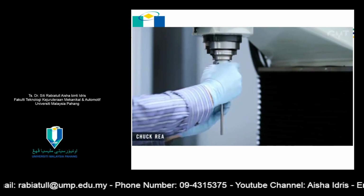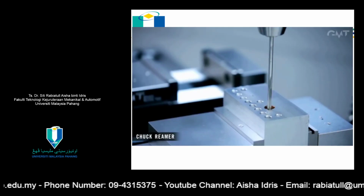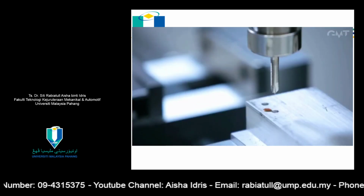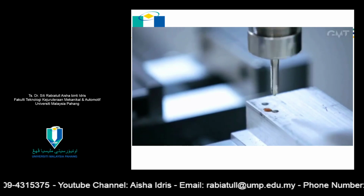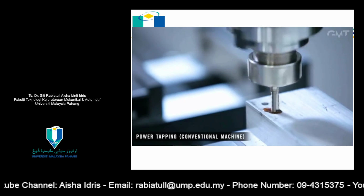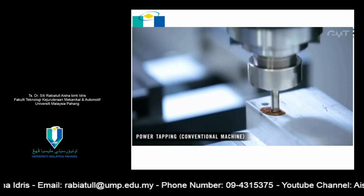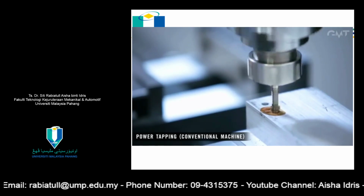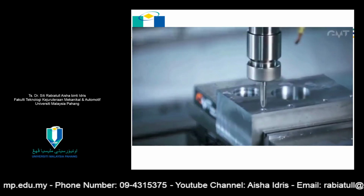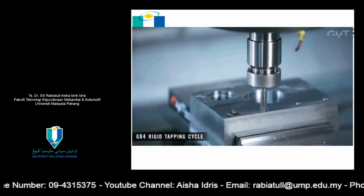Chucking reamers are used to enlarge pre-drilled holes to very precise diameters. Slow speeds as well as coolant or lubricant should be used. Power tapping is a fast way to tap holes on a conventional machine equipped with a quill and a 3-phase instant reversing motor. Synchronized rigid tapping on a CNC machine is accomplished using the G84 canned cycle.